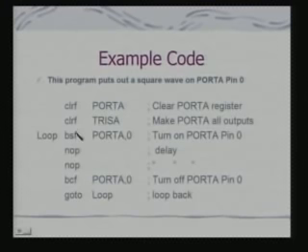Then the next part is very straightforward. We are just setting a particular pin, pin 0, and then we go into a NOP, a delay, then we clear that bit, and then we go back and loop through an infinite loop. So, I should get a square wave, and depending on the delay, I have simply used NOP. I can add more NOPs here as well, and depending on the delay, I can vary the period. I can also vary the duty ratio of this square wave.